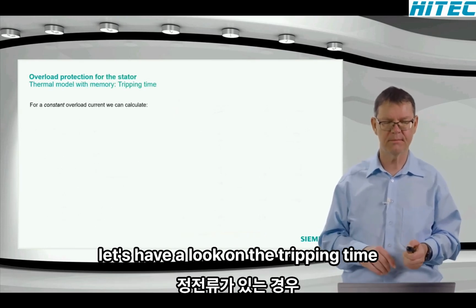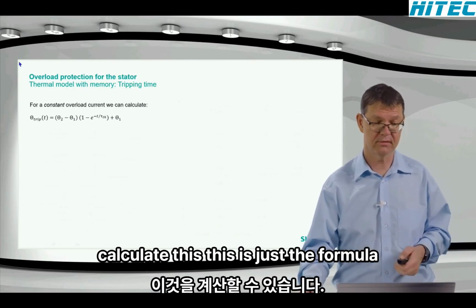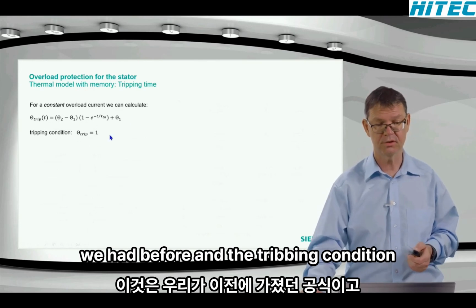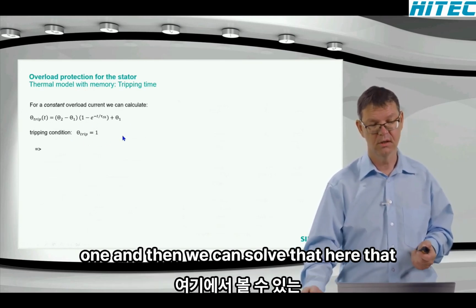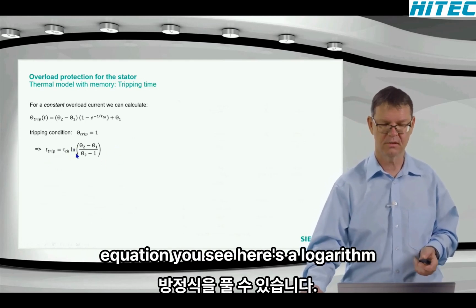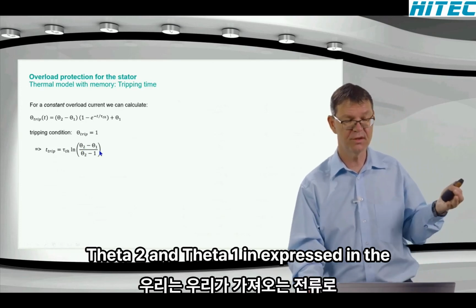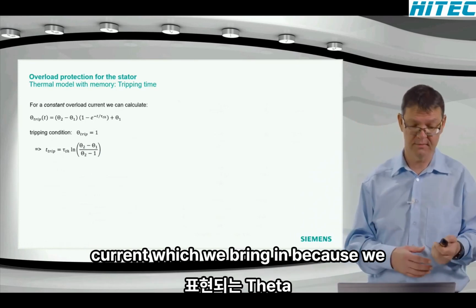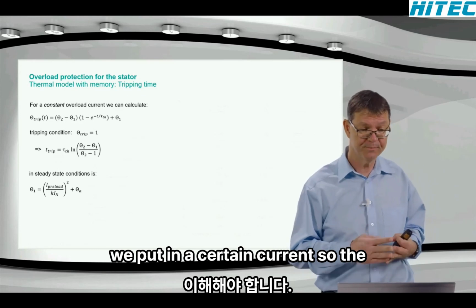Let's have a look at the tripping time. If I have a constant current, we can calculate this. This is just the formula we had before, and the tripping condition is 1. The tripping temperature here is 1, and then we can solve that here. That equation, you see here's a logarithm inside. Now we need to understand what is theta 2 and theta 1 expressed in the current which we bring in, because we want to know what is the behavior when we put in a certain current.